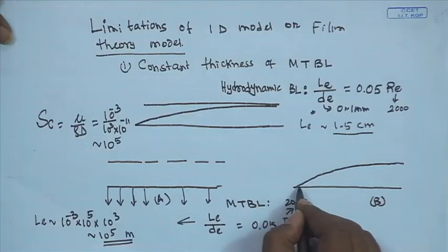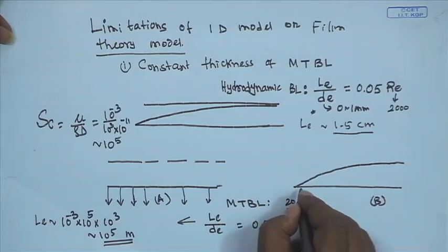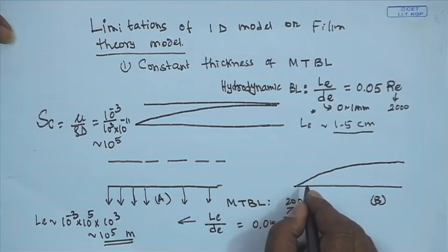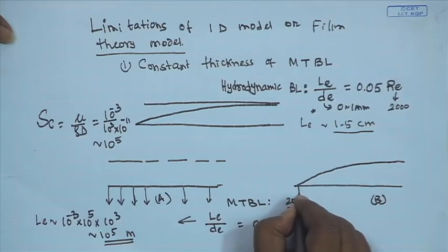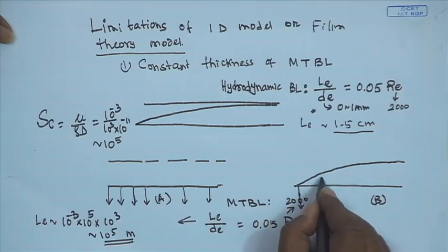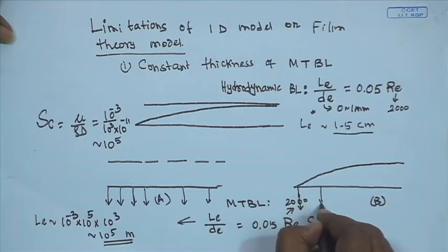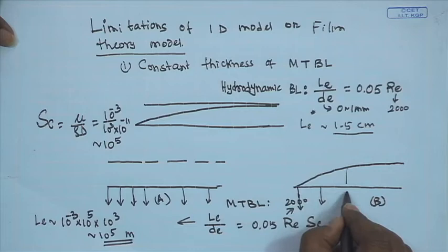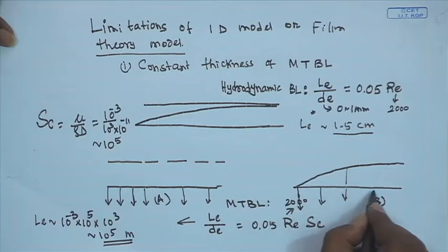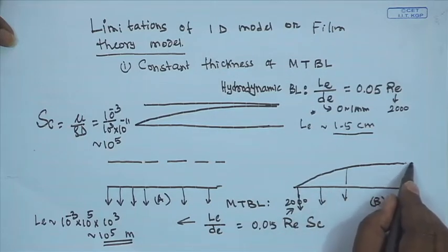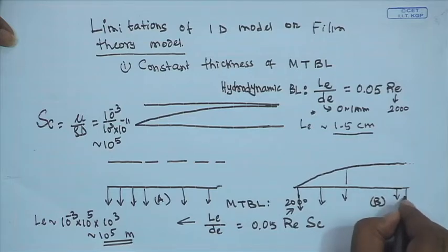Now, let us look into the interpretation of the developing boundary layer. If the boundary layer is developing, then at the beginning of the channel, the thickness of the boundary layer is less. So, it offers less resistance against the solvent flow, and the solvent flux will be maximum. As the thickness increases, it offers more resistance and the solvent flux is lower. As you go down across the channel length, and later when its growth is almost sluggish, you will get an almost constant value of permeate flux.